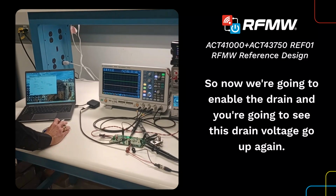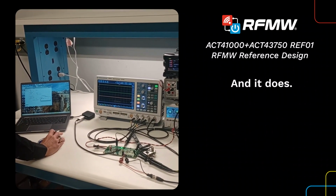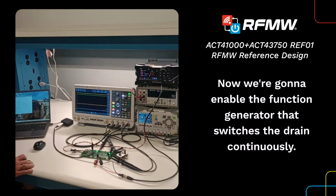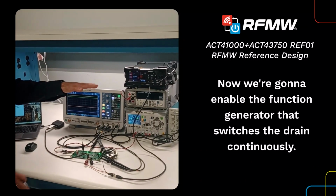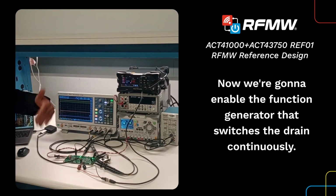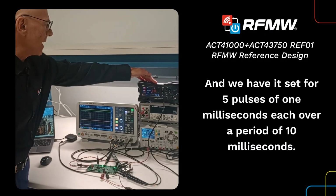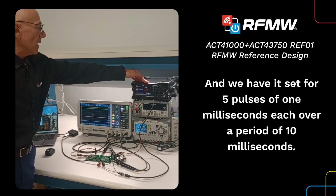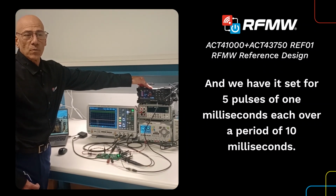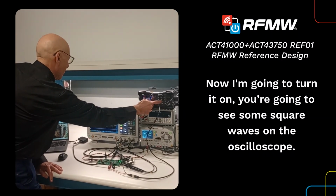So now we're going to enable the gate, and you're going to see this gate voltage go up again. And it does. And now we're going to enable the function generator that switches the drain continuously. We have it set for 5 pulses of 1 millisecond each over a period of 10 milliseconds. So now I'm going to turn it on. You're going to see some square waves on the oscilloscope.